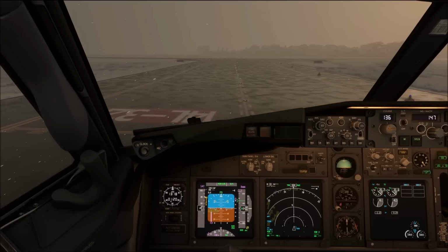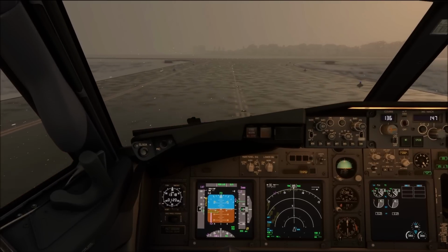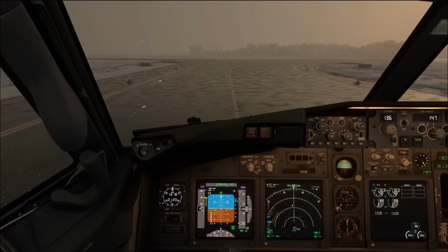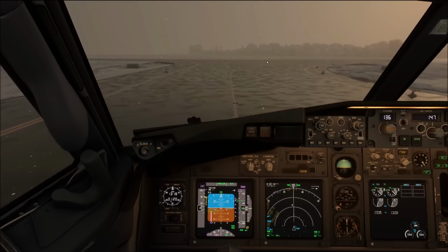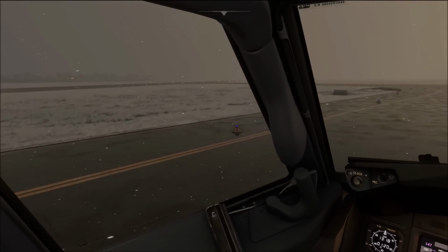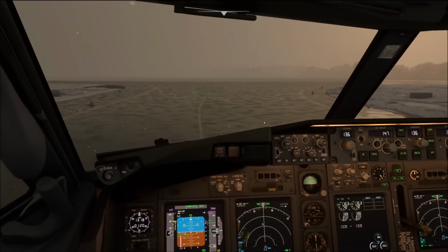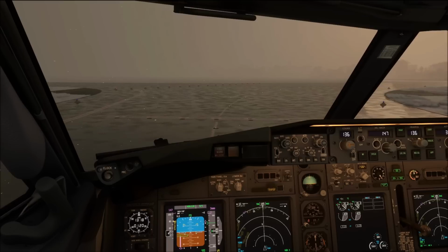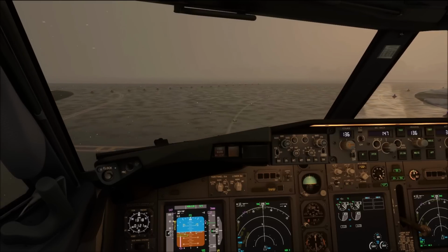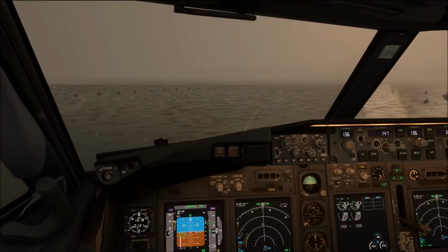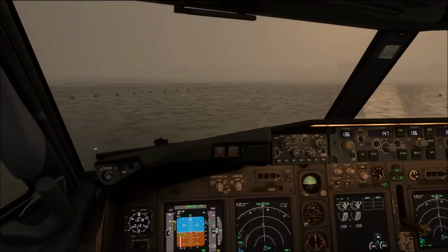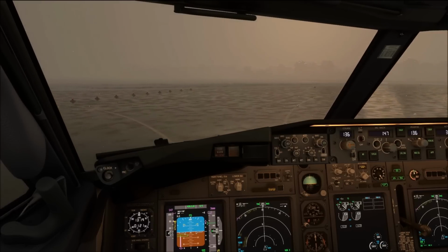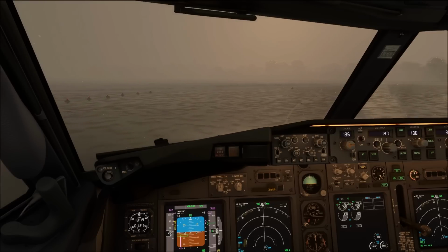So here's the problem. That last third, because it is so rarely used, might be in a significantly worse condition than the actual first two thirds of the runway. Therefore, when you are having an airplane roll to the end of the runway, be sure to keep those thrust reversers out until your stopping really is assured. Until you are really sure that you can stop. That is what I wanted to say.